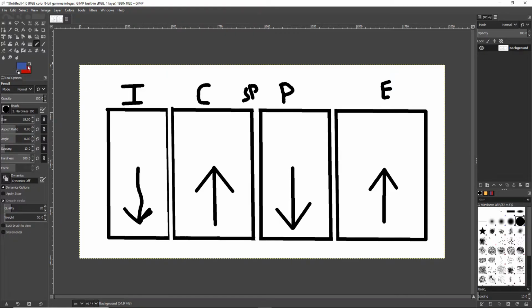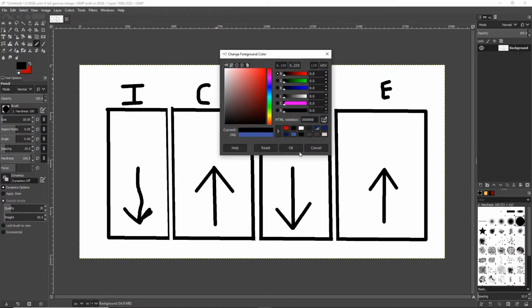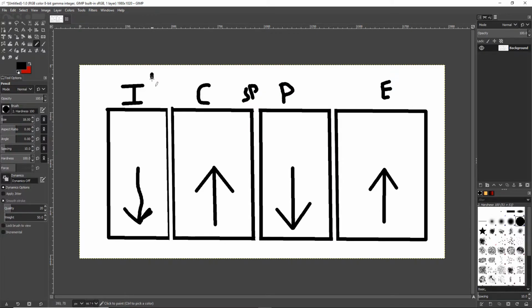And then open or closed, this is how we draw it. So let's pretend this square up here is the top of the cylinder. A closed valve looks like this. An open valve looks like this, because the camshaft has pushed it away from the cylinder head, and now we can have air and fuel or exhaust go by. If this is hard for you to conceptualize visually, I have one on the table at school. I would love to show it to you. Remind me next time we're in class.